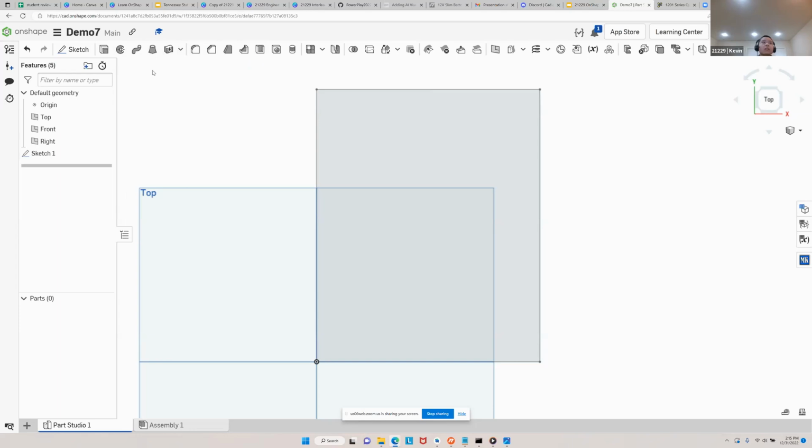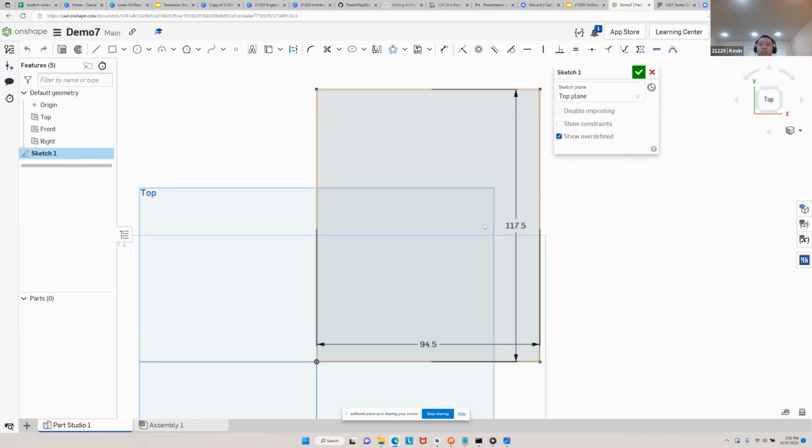Yeah. They are not in the sketch. Have you created a sketch yet? Yeah. You need to double click on your sketch to enter the sketch. Oh, that got it. Does that solve it? Thank you. Okay, now you can see the corner rectangle tool.